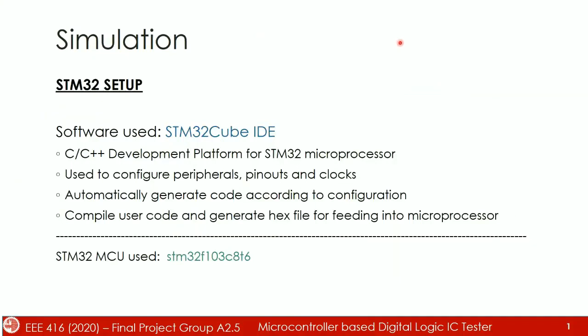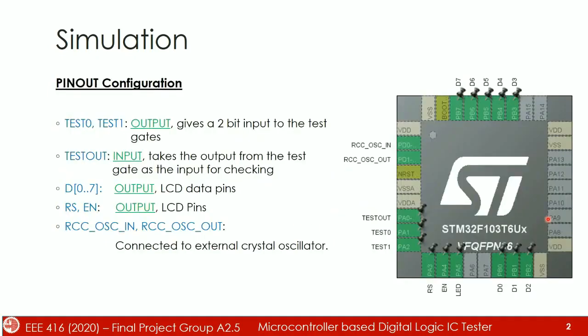I am Fahim Mashur and now I am going to talk about the simulation part of our project. For our project we have used an STM32 microcontroller, STM32F103C8, and for configuring the microcontroller we have used the software STM32 Cube IDE. We configured the pinout and clocks and finally generated code and compiled it to generate a hex file which will be fed into our microprocessor for execution.